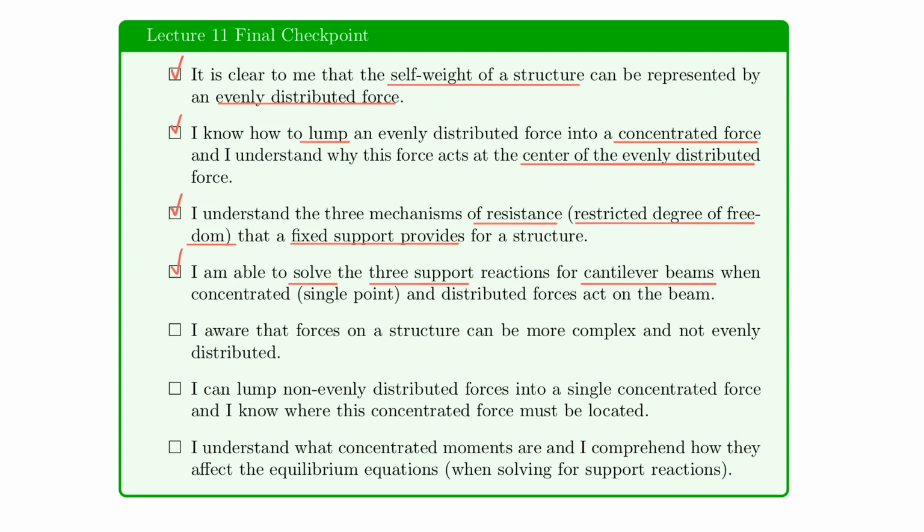But we also learned that the system can be much more complex if you have non-evenly distributed forces. So we are aware that this, of course, is all an idealization and that in real life it can be more complex. In fact, when it becomes more complex, you may end up with non-evenly distributed forces, but you learn that they can also be lumped up into a single concentrated force simply by finding the area under the curve and then finding the location, so you understand where this concentrated force must be located. At least conceptually, we talked about that.